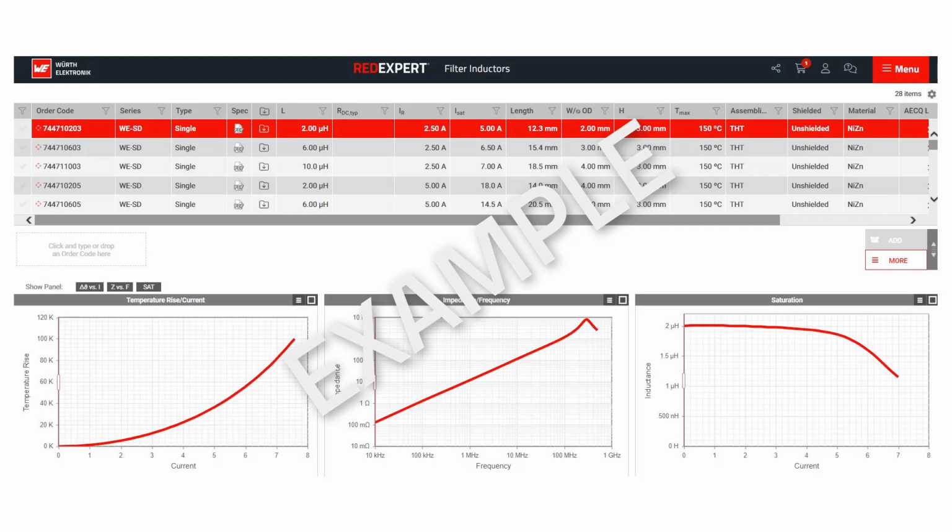Actually, you can put all your data here in the parameters, where you want to know exactly which inductance value you need according to your duty cycle and your switching frequency. And if you keep the ripple current not higher than 30-40%, you may have quite a good solution.